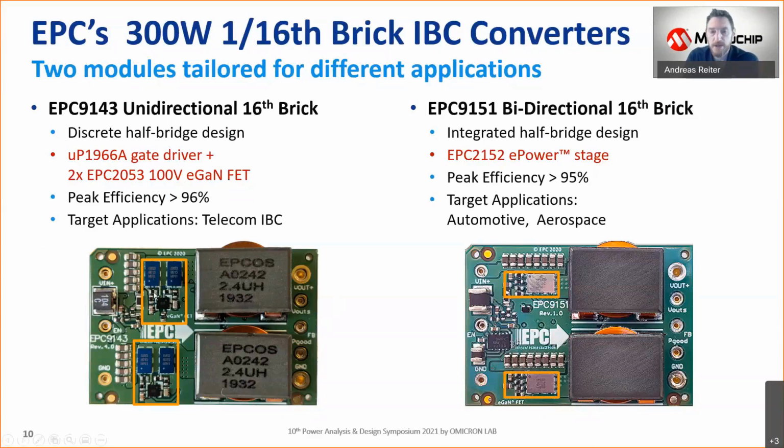So we always stay slightly below that. Now as everything is integrated, we can really push the envelope to the limit and operate the switches as fast as possible. The downside here is that because of the technology and the packaging, or let's say the chip design, the integrated devices have a slightly higher RDS(on).